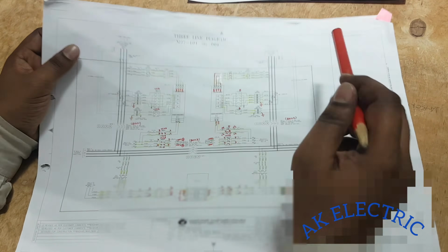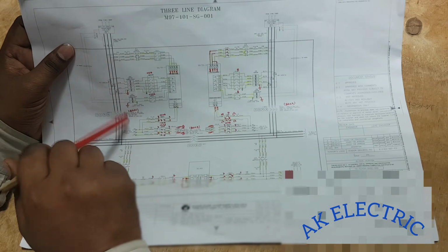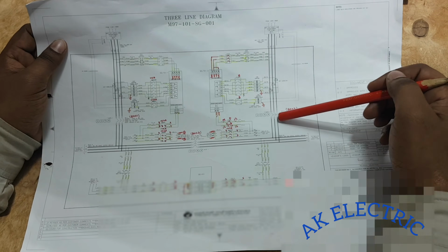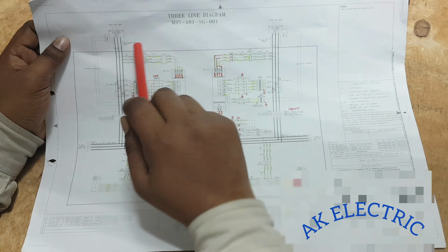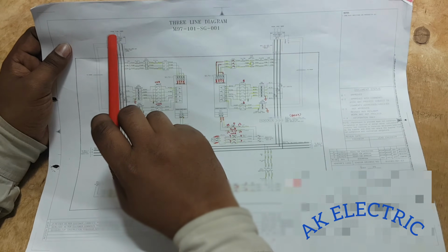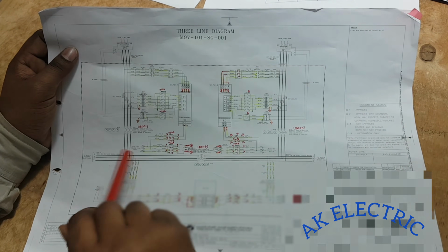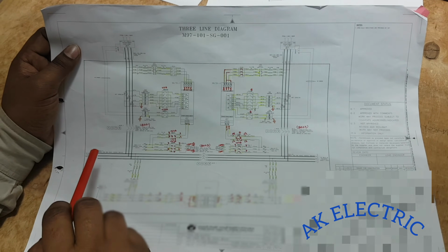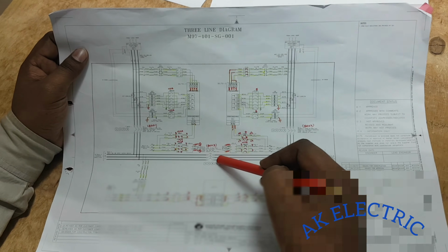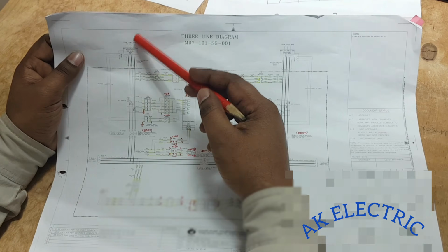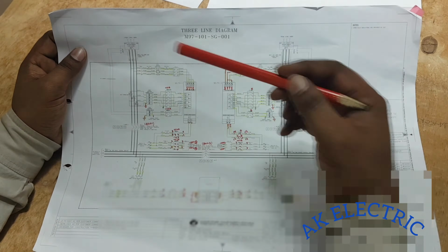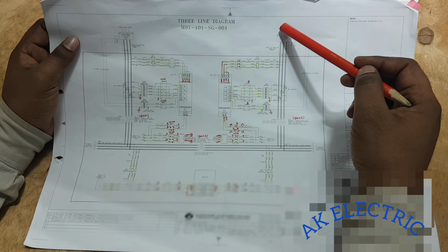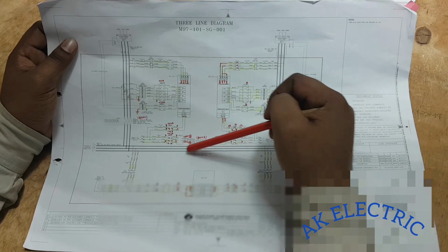Okay, see now, once we energize this bus A through incomer 1, next we energize this bus B through incomer 2. So if any power loss, suppose this transformer incomer 1 breaker is tripped, bus A will be de-energized. So bus A connected loads will be affected. That should not happen. For that, this tie breaker should automatically close. So if incomer 1 power loss, this breaker will trip. At that time, this tie breaker should automatically close, so that this incomer 2 supply will transfer to bus A through this tie.